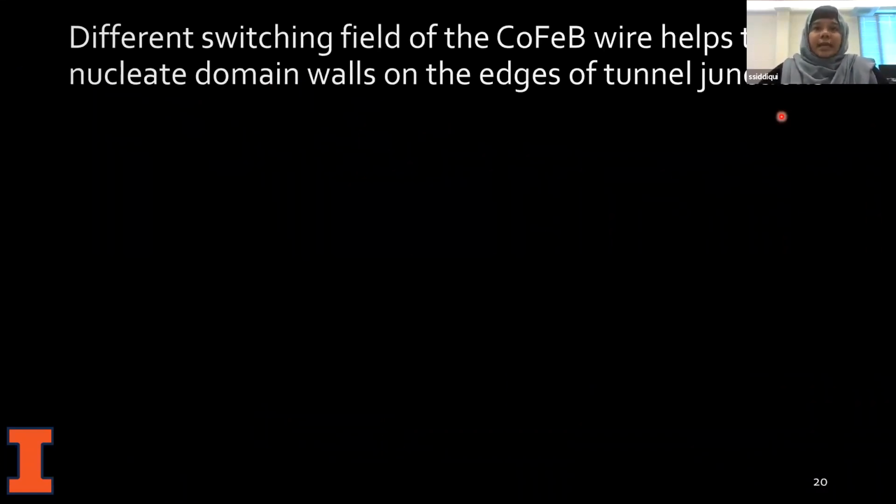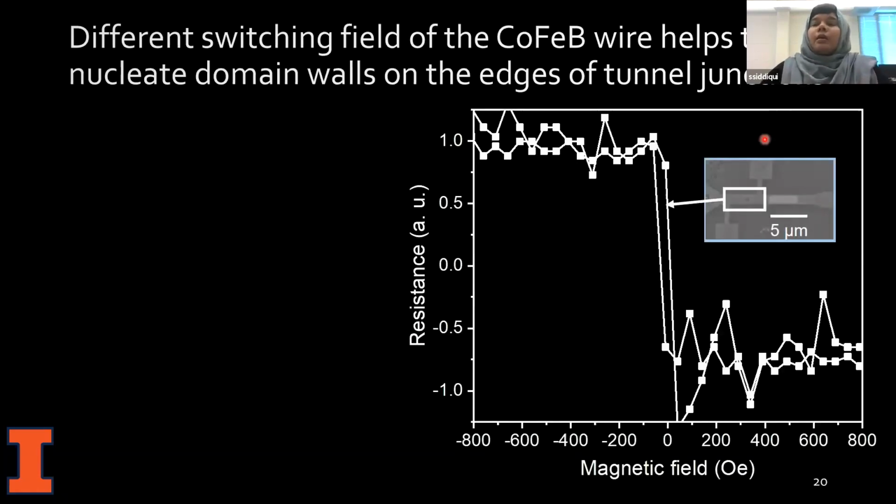Now, in the previous slide, when talking about the in-plane type of logic device, I showed that we created this curvature to nucleate the domain wall by using an applied field. What about how we can generate the domain walls in this kind of perpendicular magnetic tunnel junction? So now we look into this free layer more closely, and what we see is that whenever we etch away the reference layer, the free layer switches with a very small field, roughly about 20.